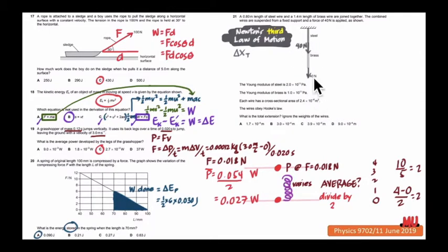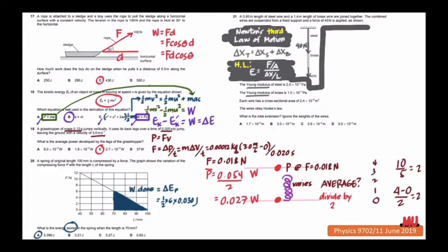The total change in length, or the extension, is the sum of the extension of the steel and the extension of the brass. We are given the Young modulus of the two materials also, and from Hooke's law, we know that this constant equals the stress, or force over area, divided by extension over the original length L. We can write this equation as E equals F over A. Instead of dividing, we multiply by the reciprocal, L over extension delta X, which when manipulated further gives us an expression for the delta X.